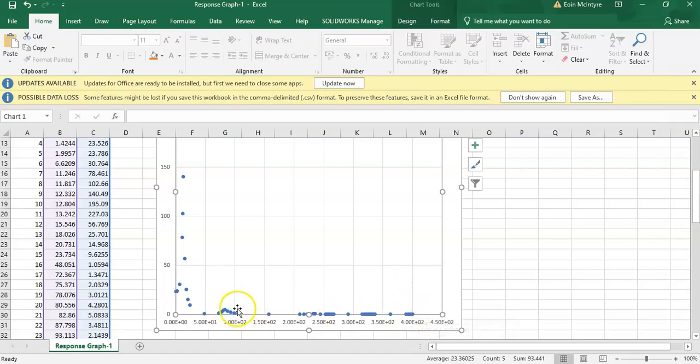Each of those data points are clustered logarithmically, so the points are more concentrated right at the natural frequency point. That was the option we set up in the study properties, to have 10 data points per natural frequency and have them logarithmically distributed. You see there is a point in here between each of the natural frequencies as well.